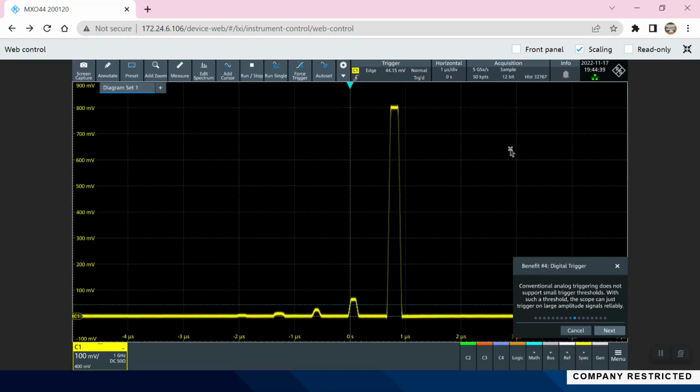And because your overall signal has small elements and big elements, you can't make this signal any bigger on your screen to try and capture it. So you're really limited here by your trigger sensitivity, but not with a digital trigger. And you're certainly not going to be able to scroll down and trigger on that next signal.